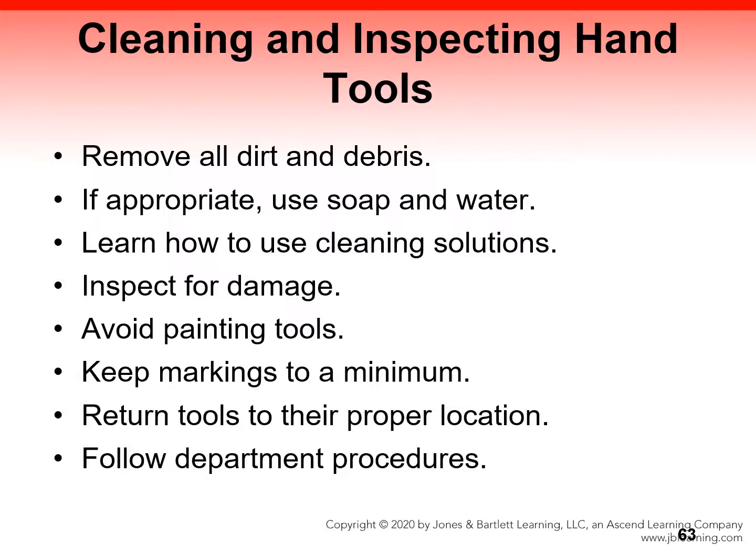Before any tool is placed back into service, it should be inspected for damage. Avoid painting tools, because this will hide any possible defects or visible damage. Keep the number of markings on a tool to a minimum. To clean and inspect hand tools, make sure to follow the steps in Skill Drill 8-1 in your textbook.